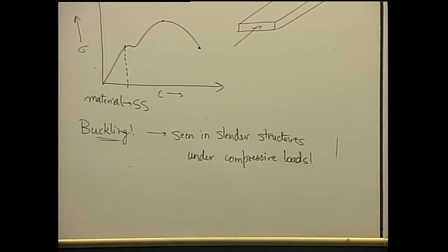Of course, if the tensile loads are very high, they also couple with the bending stiffness. That's another effect that can be discussed later, but it's not leading to an instability, right? Especially rotor blades have a large amount of tensile or axial force because of the centrifugal force. So they undergo another phenomenon where the blade stiffens as it rotates. That helps researchers save some weight because the axial load provides some stiffness. But that's not causing any instability, at least.